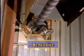In this part, we'll take a look at some common additives to natural lubricants, as well as at synthetic lubricants. Additives are substances that are mixed with oils and greases to improve their lubricating abilities. A type of dried clay called bentonite is added to thicken the grease on the bearings in these rollers. Bentonite is far more heat resistant than some other grease thickeners.